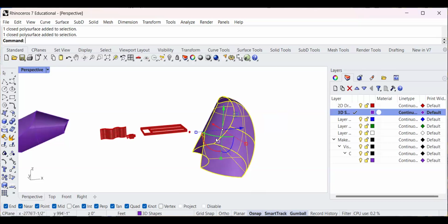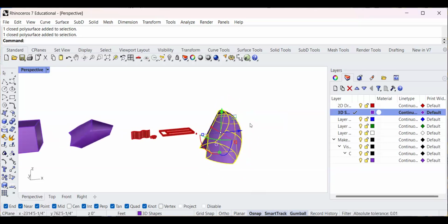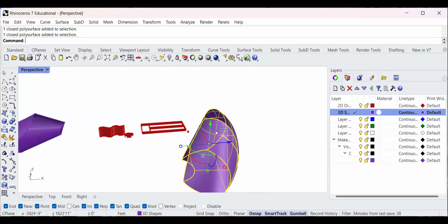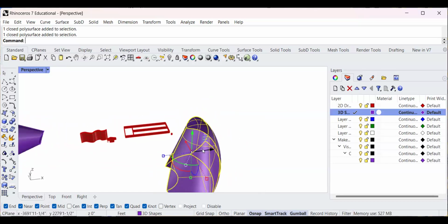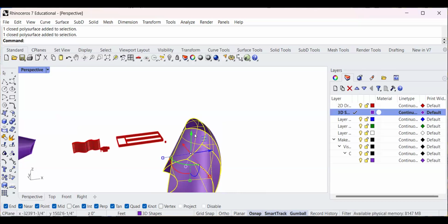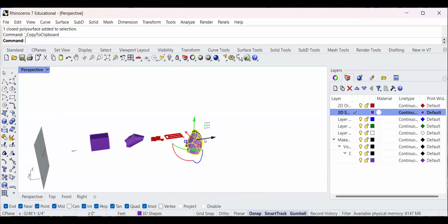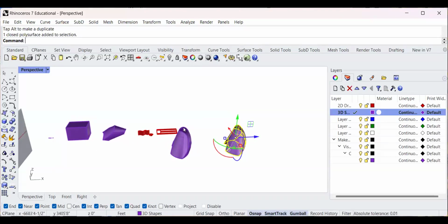You could create an STL file. This is huge. Remember, this is in feet, so we need to scale this. So I'm going to make a copy, Control C, Control V, and then here's my copy. And then I'm going to scale this just like before.